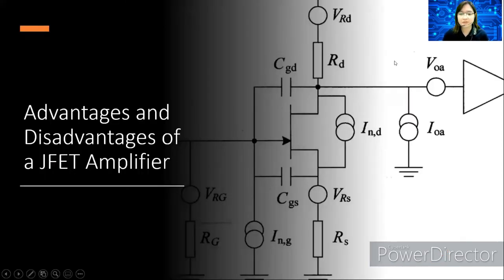So there are some important advantages of a junction field effect transistor, and there are also some important disadvantages. First are the advantages. The junction field effect transistor, or JFET, is a majority charge carrier device, hence resulting in less noise. It has high input impedance, is a low power consumption device, and can be fabricated in a small size area. It occupies less space in circuits due to its smaller size and has a negative temperature coefficient of resistance. So they possess higher temperature stability.